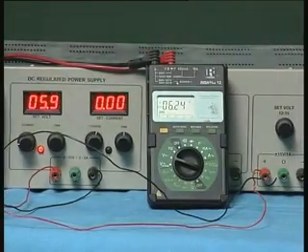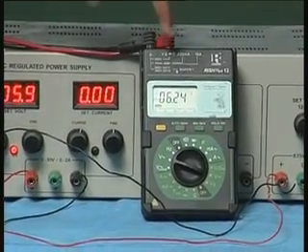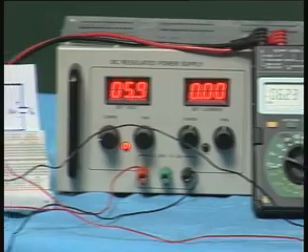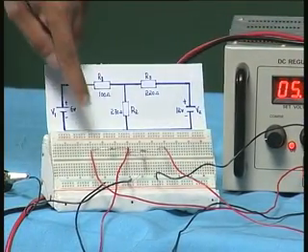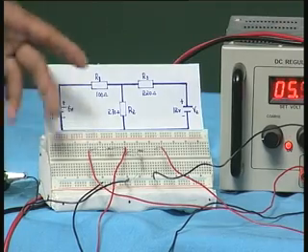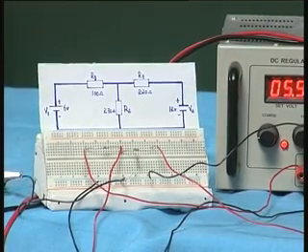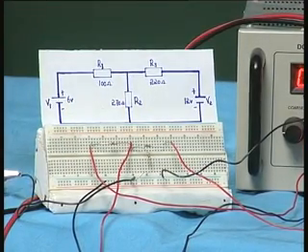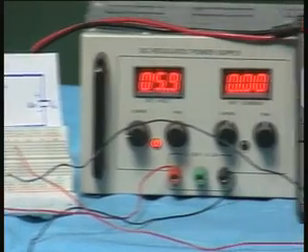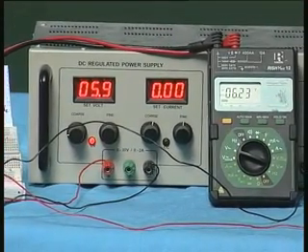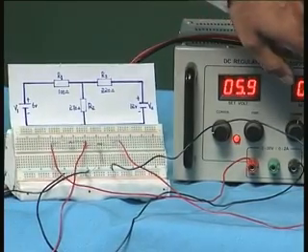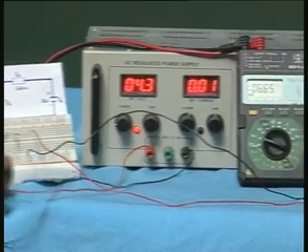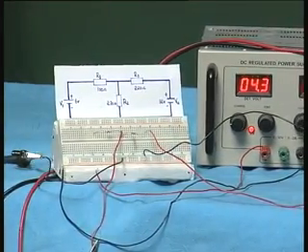I get 6.28. You remember we calculated 6.288. Now it is 6.24 or something like that here. So the value is reasonably close. Why is it different? It is not 6.288 because these resistors have a tolerance band. By now you know all resistors have a tolerance. That means 100 ohm need not be exactly 100 ohm, and 270 or 220 need not be exactly 220. We calculated 6.288 with all the values exactly there, but now they can be different because these are all preferred values, and therefore you find it is around 6.23.